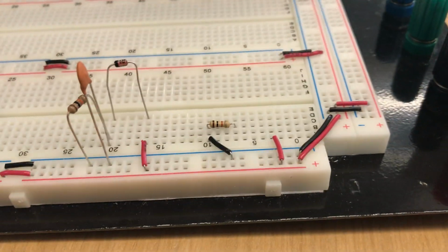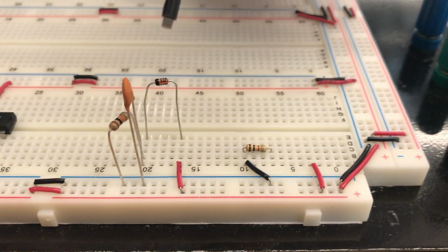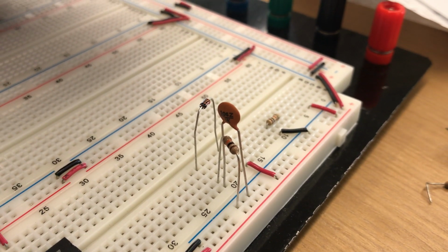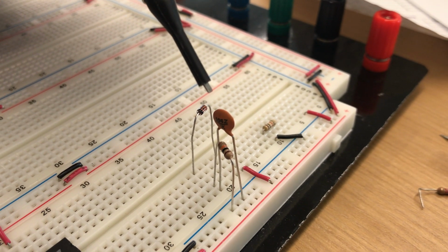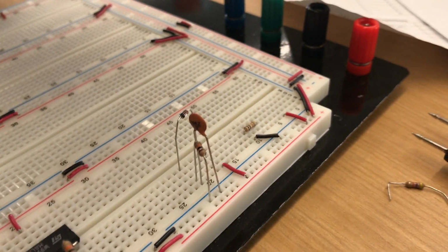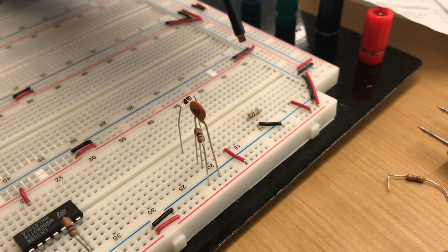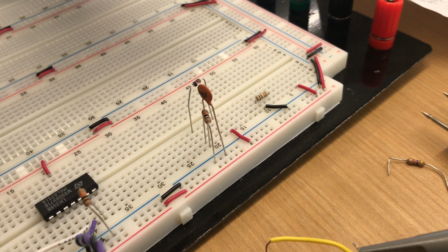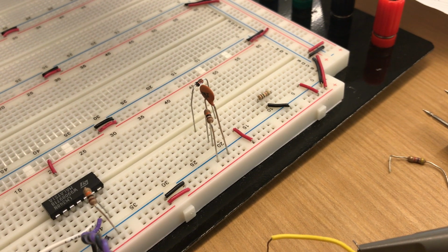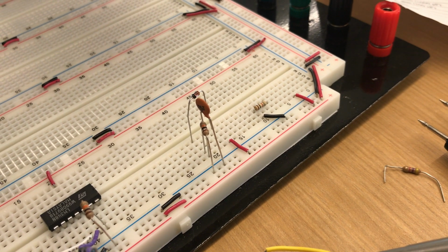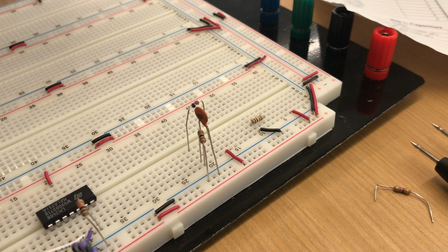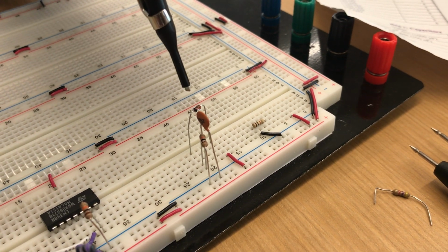In the second circuit we have the same sort of situation, except the diode feeds into a capacitor and a 10 kilo ohm resistor, which are connected in parallel to ground. We measure the voltage across the resistor, and that gives us our V out. We measure V in, and we do it with and without the capacitor. This is our passive half-wave rectifier.